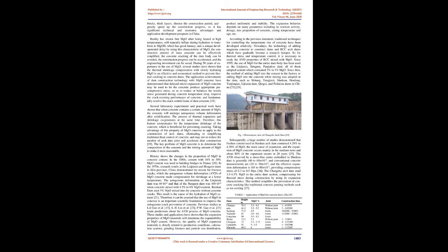Taking advantage of this property of MgO concrete to apply to the construction of arch dams, eliminating or simplifying traditional heat control of concrete, may remove or reduce the number of arch dam joints and accelerate dam construction.